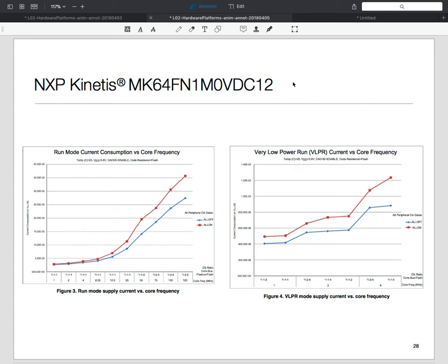On the right-hand side, you're seeing the same thing, except that now it is in that very low power mode, and it's a bit hard to read, but these numbers are a lot lower on the y-axis here. And there are similar other considerations that will come into play. Now, the main thing here is we are only changing the frequency, not the voltage, because this particular chip does not have onboard circuitry to change the voltage dynamically. Neither does it have it on the boards.